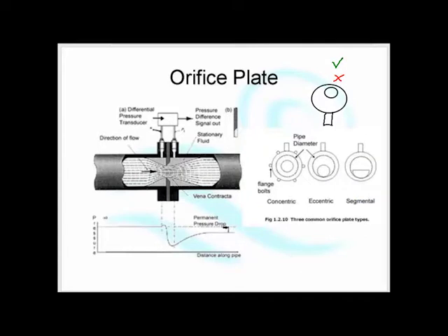Now, there's a couple of things you should know about orifice plates. The first thing is the reason why there's a little tag on the end of them. There's three reasons. The first reason is it gives you a convenient place to write down the resistance value of that orifice plate, what's called its kV. The second reason is that the little tag is on the opposite side of the hole, so it lets you know where the hole is. If the little tag is pointing downwards, the hole's at the top of the pipe. If the little tag's pointing upwards, the hole's at the bottom of the pipe.